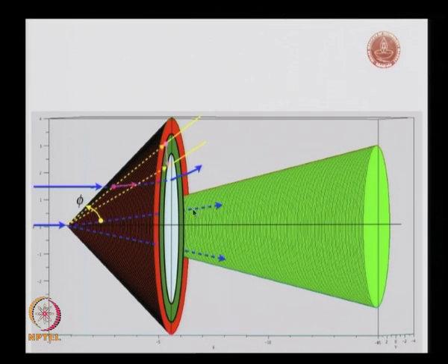So, I have a shock wave. Some of my streamlines come here and deflect, right, and then I enter here and I encounter the shock and I encounter the solid cone. Then I just come there and move uniformly over the cone and move along its surface. So, basically these are all straight lines. So, we have straight streamlines which go on the surface of this cone, right.